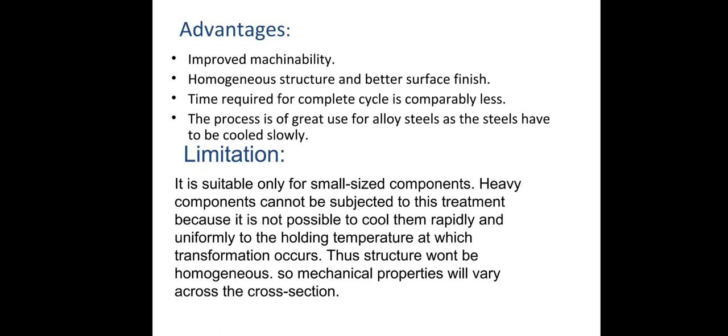Advantages: improved machinability, homogeneous structure and better surface finish. The time required for the complete cycle is comparatively less. The process is of great use for alloy steels, as these steels have to be cooled slowly.